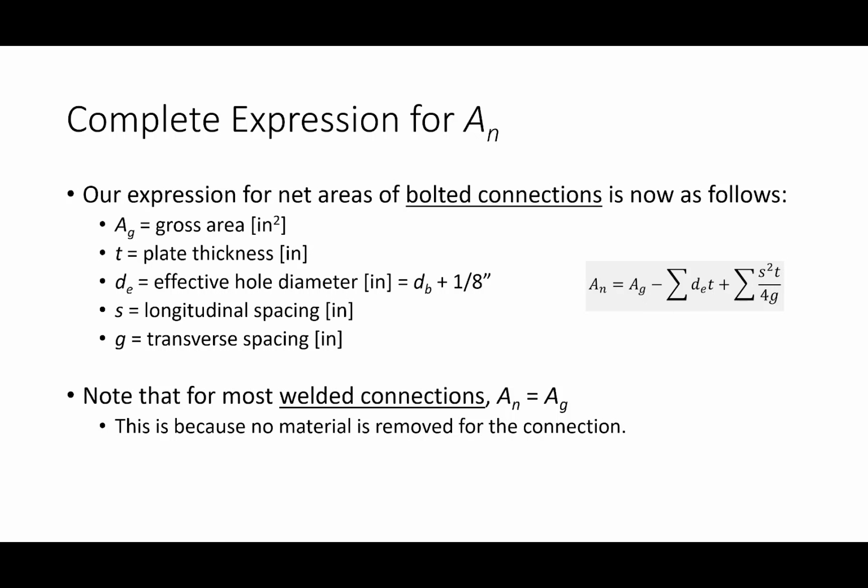Our stagger factors are S squared t over 4g. g is the spacing perpendicular to the applied load. s is parallel to the applied load. That's for bolted connections. For most welded connections, net area equals the gross area.